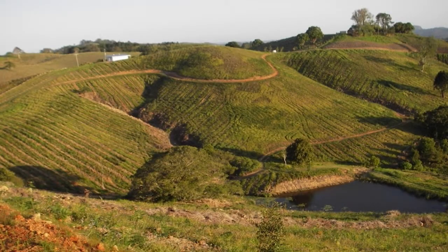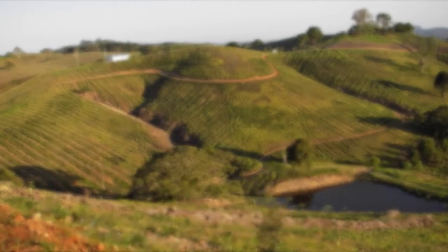On steep slopes, you may have to consider constructing cut and fill access tracks at both the top and bottom of the plantation. Access tracks may double as a fire break between commercial plantation areas and revegetation in the gully, or as a break between management units.